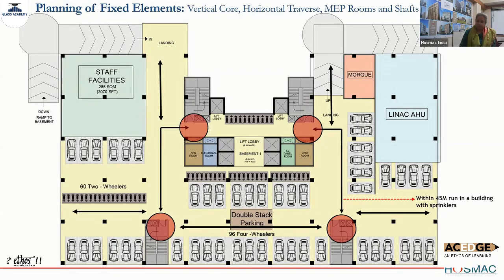So this is a basement of the same plan. Between two cars, the distance is always 6 meters for cars to reverse and then leave. Again, the routes must be very clear. A symmetrical design works well, no doubt about that, because staff is then able to acclimatize with where to go, and even the public. So these zones get developed. It's always a good thing to have continuity in design as well for such complicated hospitals or buildings.